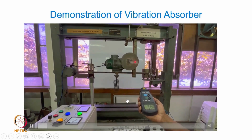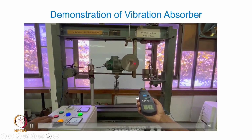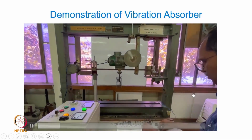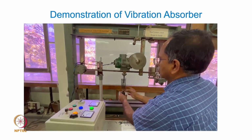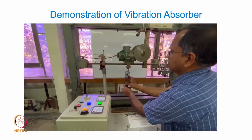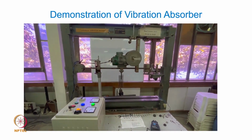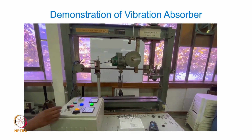So actually there are stoppers here which limit the vibration of the beam, and one can actually listen to the third sound when it starts hitting the stoppers. Now what you notice is that we are attaching a carefully calibrated mass, so that the natural frequency of this attached spring mass is the same as the natural frequency of the parent system, or the operating speed, that is 165.